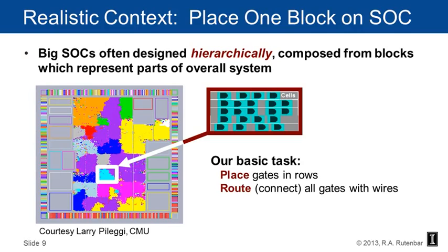And what's being shown in this particular picture of an SoC that's in the middle of being designed is there's a lot of pins around the edges, and those are all the little slice things with the little colors. And then there's a bunch of blocks inside the SoC, and some of them have a colored border, but they're gray. Those things are actually big memories, and you don't get to play with their insides. They get generated by some other kinds of CAD tools. But the things that have blobs of primary color, those are actually blocks that are being placed.